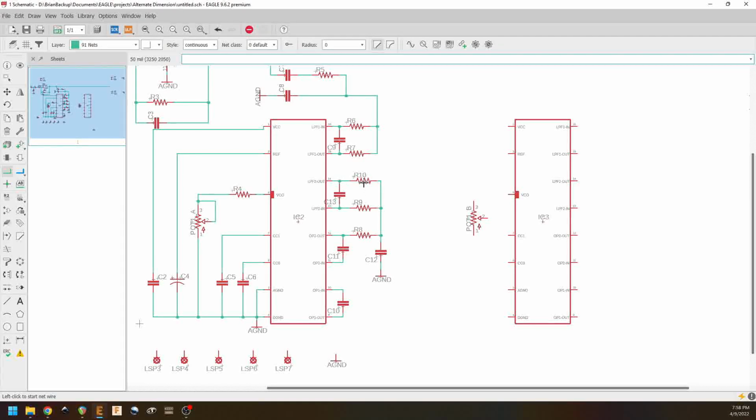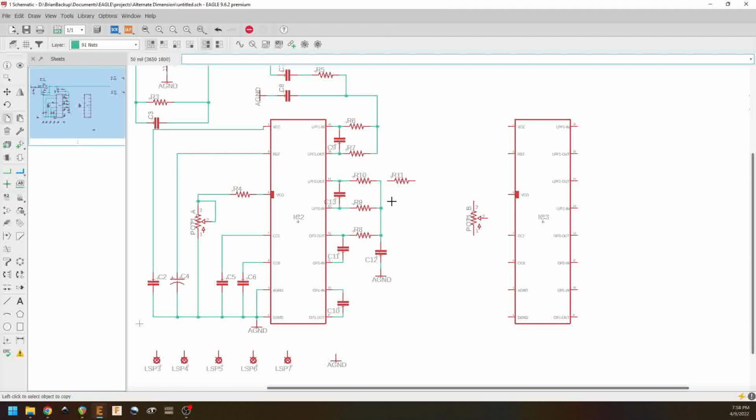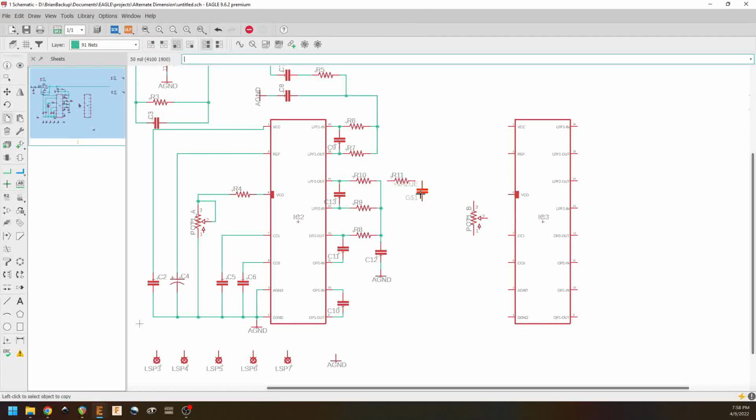So first, we're going to give this guy a little RC filter. Just really basic. This is how a lot of the commercial pedals that say analog delay or analog voiced delay voice it for analog: they're rolling off some of the high end from the repeats. This guy being an RC filter is just going to come down here like that. Beautiful.